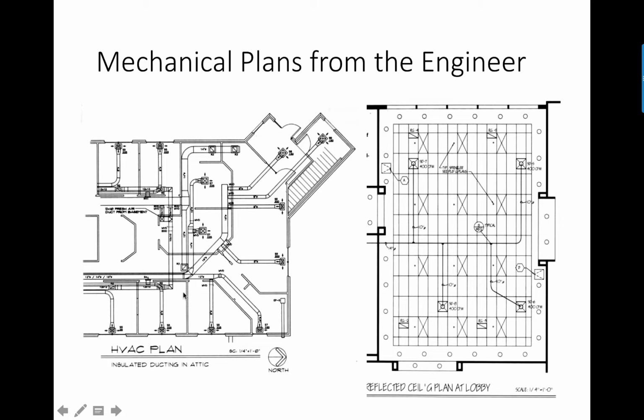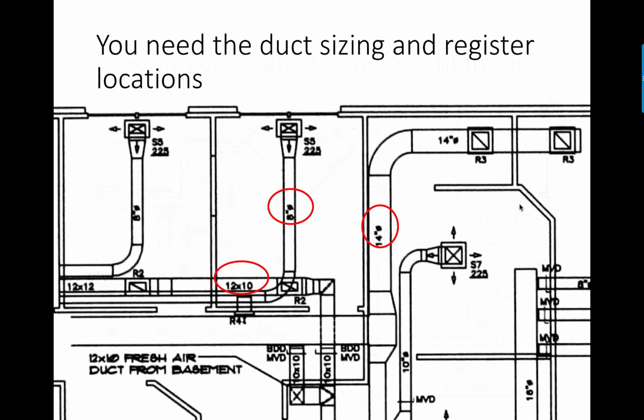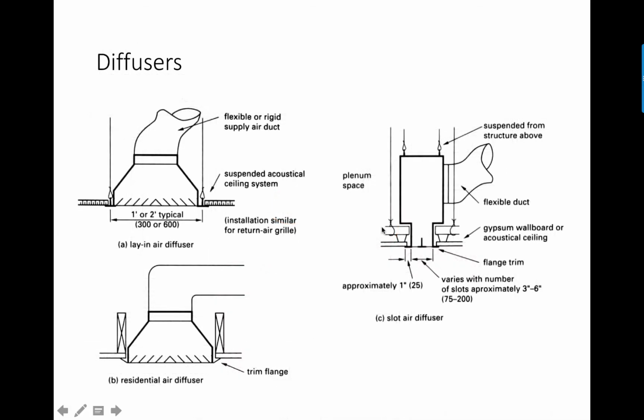And you can see here, this is an HVAC plan that I swiped from somewhere or other, that overall they show you the duct sizes, and then within each room they may actually indicate the duct size more abstractly. This is a 10-inch diameter. It looks kind of like a dryer hose. And when you zoom in on that, you can see these are the sizes of the duct. This one is 8 inches in diameter, whereas this is 10 by 12.